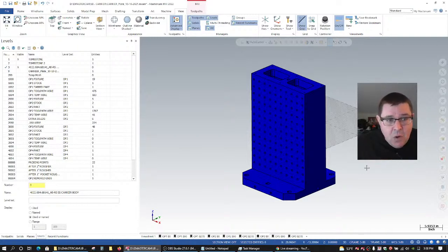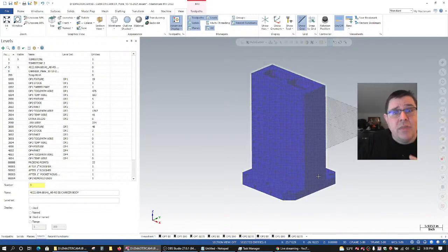But what I'm talking about is actually having a detailed model with the full clamp in it. But for toolpathing and for verification, I just want a box. I want a rectangle that represents the overall size of that clamp, but does it with 12 triangles. Right? So a 6-sided cube or a 6-sided rectangle can be represented in its simplest form, in terms of a mesh, with 12 triangles, right?